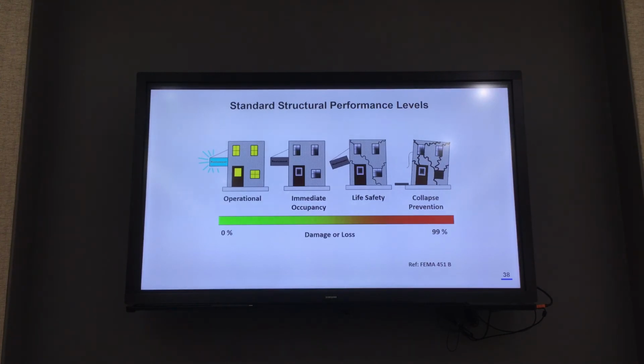No. When we consider the spectral acceleration, we consider all the maximum earthquake accelerations to draw the spectral curve. So it might be another reason. Yes, 2/3. No, that is already the average. That is from the average of all the earthquakes already. 2/3 is only to bring it down to a design level, an arbitrary level.